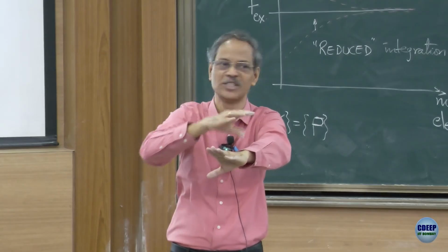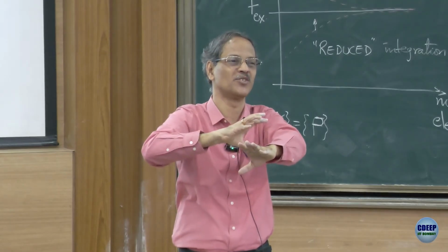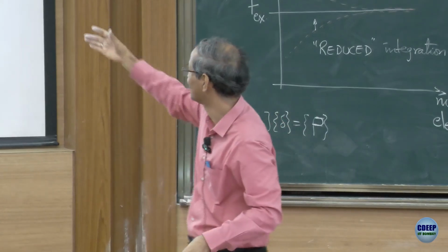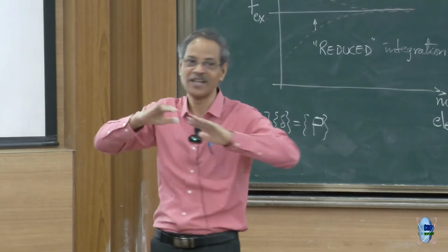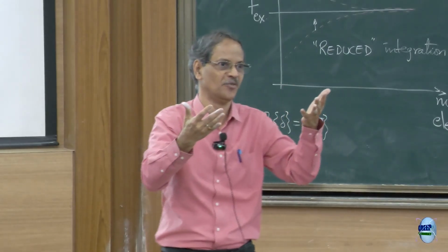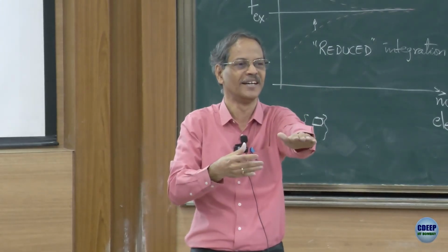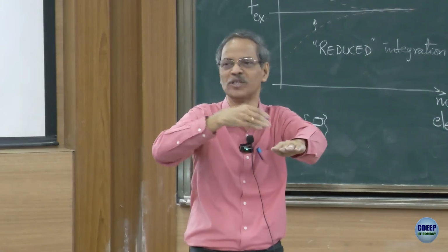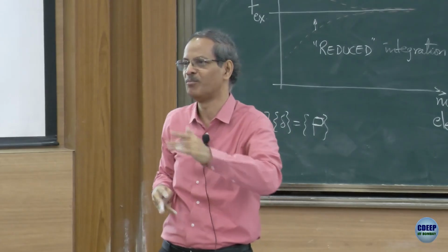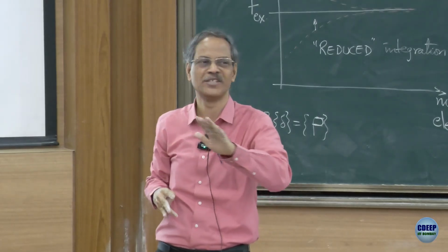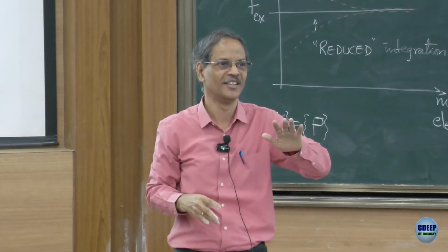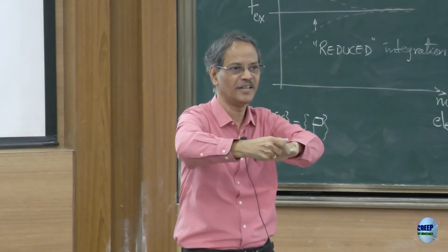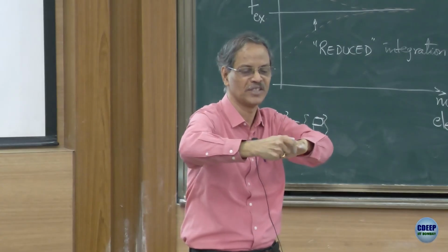Okay. So this structure tends to become stiffer. So there will be additional terms other than these in such problems, because the governing differential equation which we solved for, say, a beam had only up and down displacement. We proposed the simple Euler-Bernoulli based beam bending element, right. So we didn't consider anything more complicated than that. So there will be additional terms because of this now axial